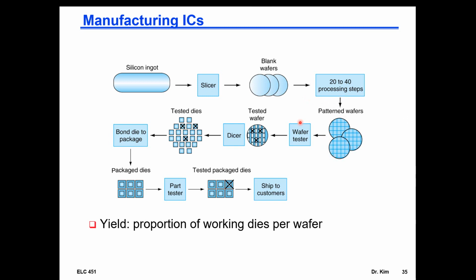your chips. Okay, and they get tested at the wafer level, and the ones that don't pass the test get probed. The chips have pads, and there are probers that come down with needles and probe, and they mark the bad chips with ink. You're always going to have bad chips. Why? Because you will never have a zero defect pure single crystal silicon. There's always going to be some level of intrinsic defects, and if there are intrinsic defects, then the semiconductor technology is not going to work, and there is nothing you can do about that. That's just a function of the raw material itself. But the ones that are good, after you dice, you basically cut the chips up and down, left and right.